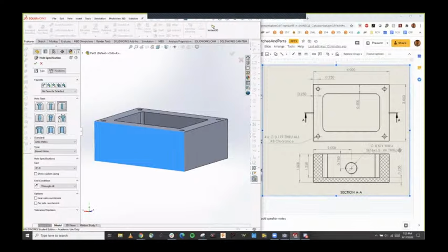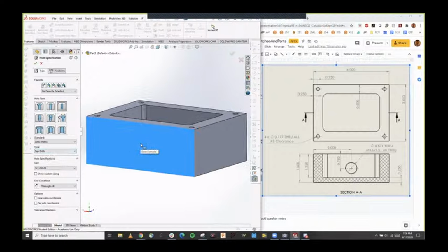This is standard GD&T nomenclature. You don't necessarily have to understand this right now, or depending on your career, maybe never. But when we're reading a drawing like this, this is standard GD&T, which means that this is an M16 screw, and the 1.5 is the thread pitch, which means that this hole is a pre-tap hole. So we want to select a hole, and we want to select tap drill. What tap drill does is make a hole that is the size you need before you tap it.